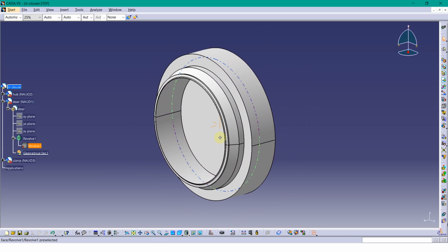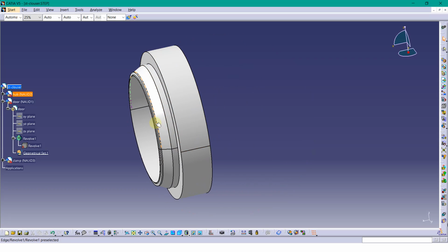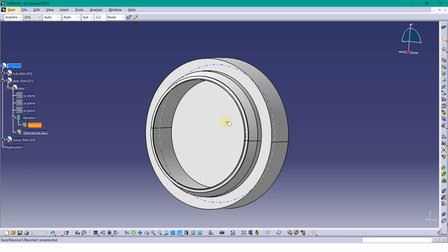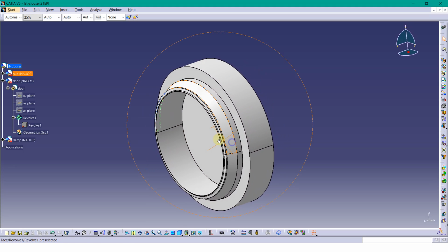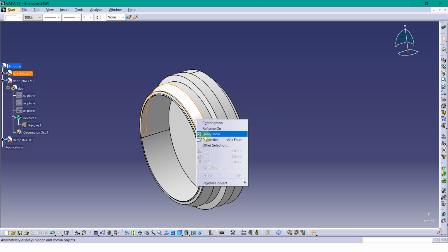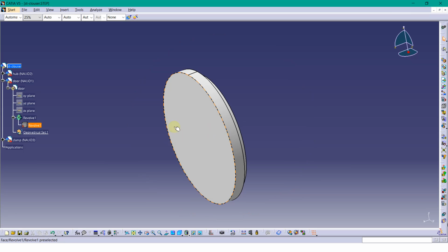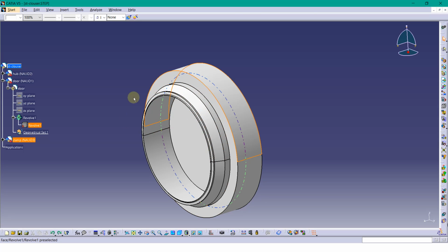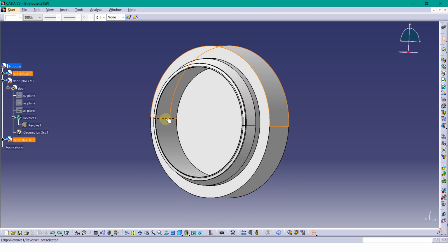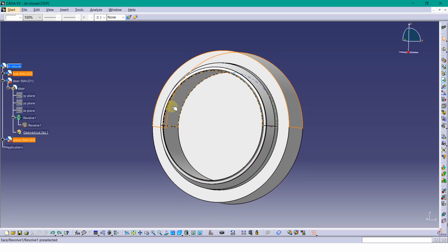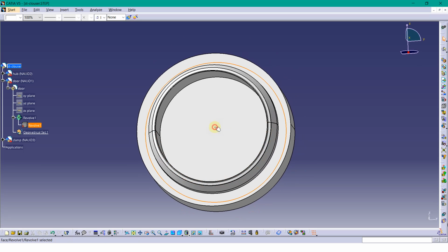Here we have a closure that is used to end an oil pipeline. This is a 48-inch closure that consists of a clamp, a hub, and a door. These three parts constitute this closure, and at this region it is connected by weldment to the pipeline, and the pressure is applied at this surface and this surface.